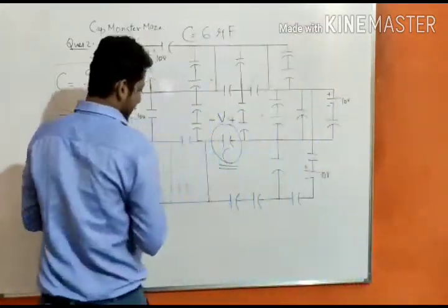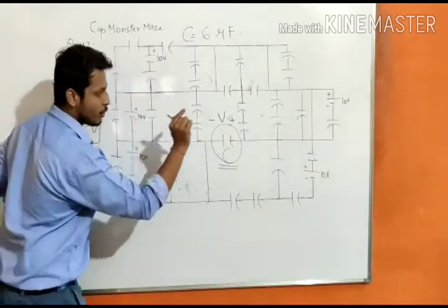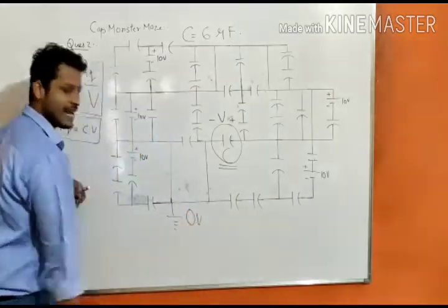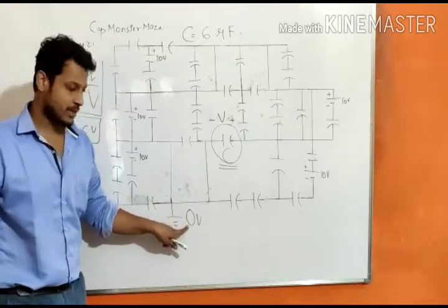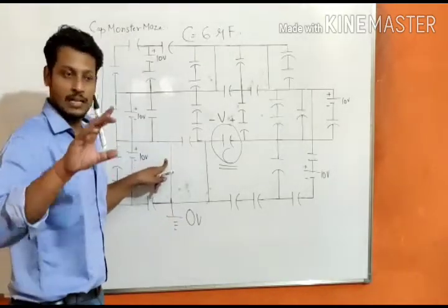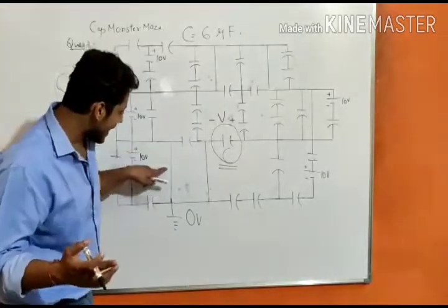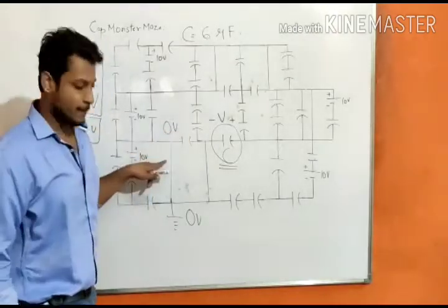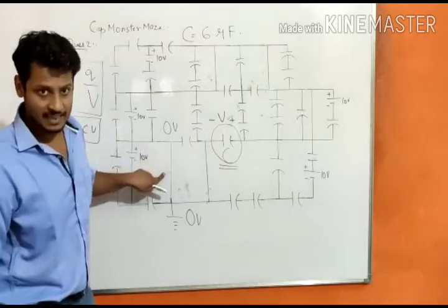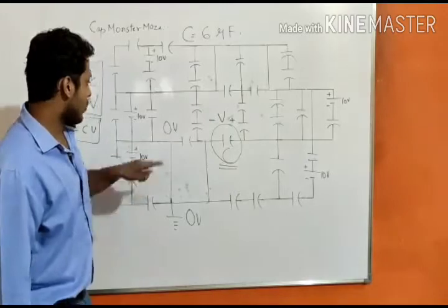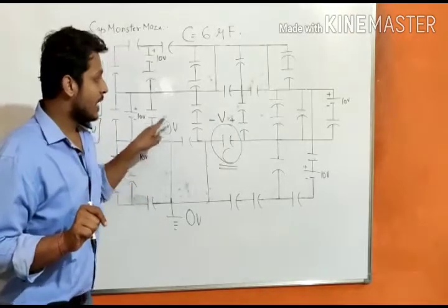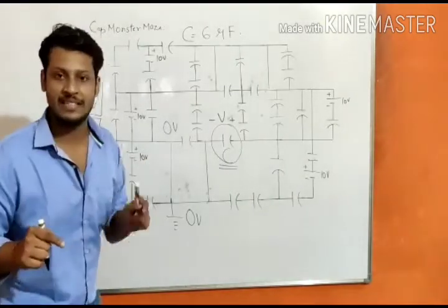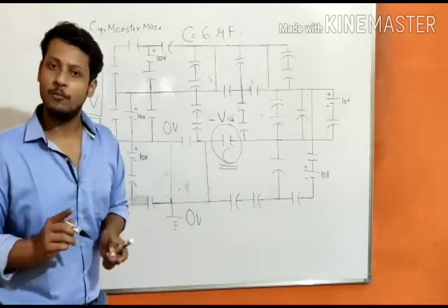We have seen that we have to find out the voltage. Now, let us assign this point 0 potential. In this line no capacitor is connected, so according to the node voltage method, this entire line will be at 0 potential. Now the best way to solve this problem is to move in such a way that you don't have to encounter any capacitor. Only then can we write the voltages.